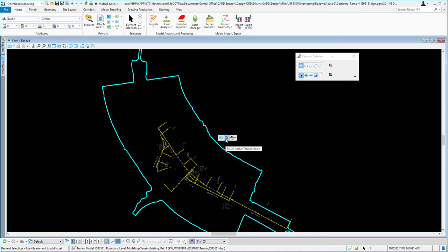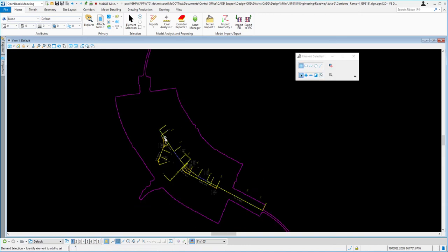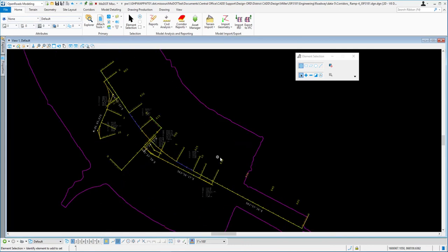And what this does for us is it ensures that when we place templates out here that have in conditions, meaning it has a fill slope or back slopes or ditches or anything, that they solve. Any kind of in condition will go out and seek ground and solve.